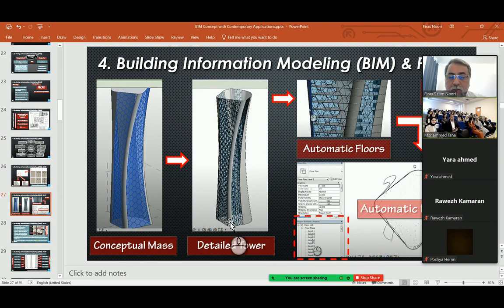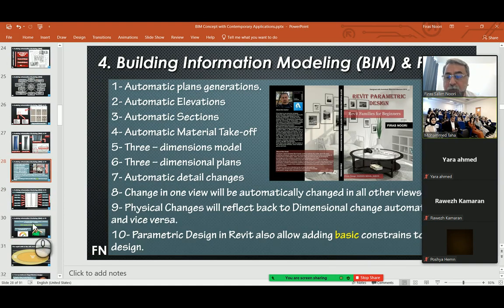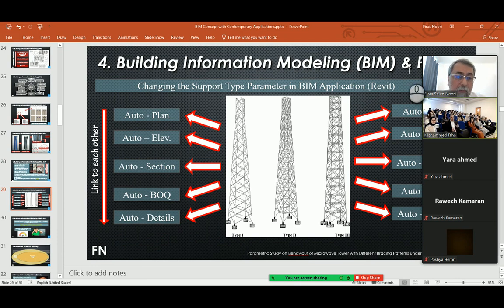I'm not going to compare myself. If you want to do that geometry in Max, you have to slice it with the section tool, then push the section every 4 meters manually, and then export that to CAD to get your plans, because it doesn't have any typical floor, as you can see from this geometry. I would not be happy to do this job in AutoCAD and Max, because it can take forever, while it can take a maximum of 60 minutes to do the same geometry if you use Revit or a building information modeling platform.